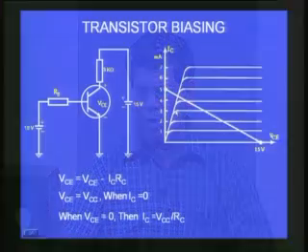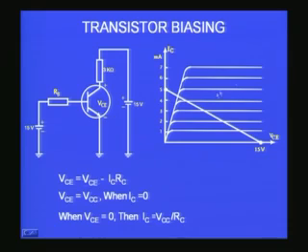Then you should try to position the operating point of your transistor on the characteristics at a carefully chosen operating point. One has to choose that operating point carefully. How do we choose? Now, that is what is known as the biasing of the transistor. This technique is called biasing. Putting the amplifier or the transistor at a given operating point with reference to its output characteristics is what we call in general transistor biasing. Now, if you look at the figure, you can see the output characteristics drawn here, very familiar to you by now, and you have to put it somewhere here. This is the active region, you have to put your transistor somewhere here.